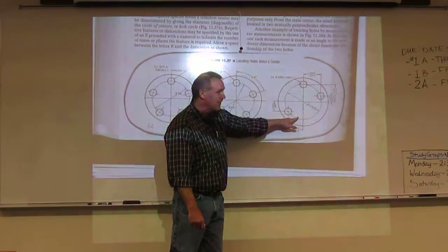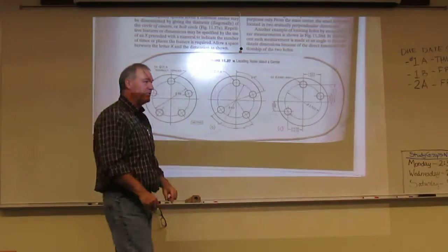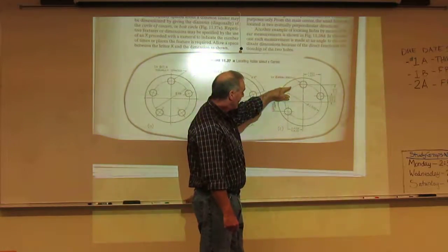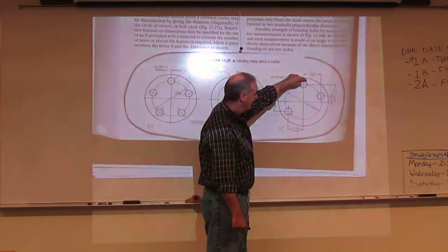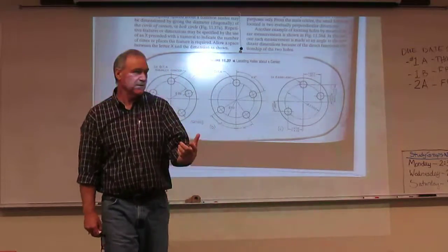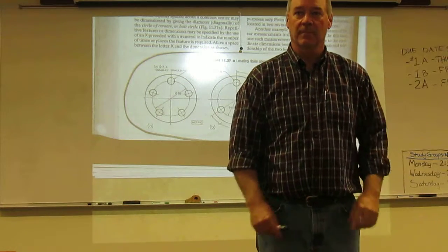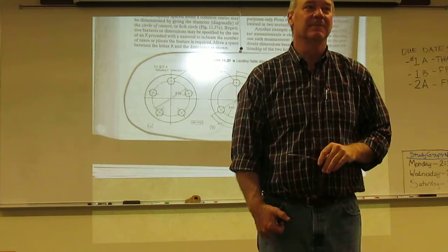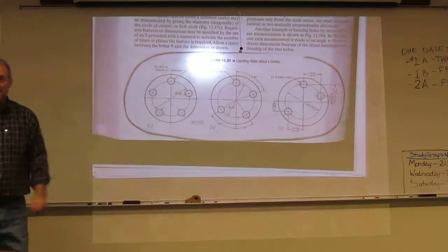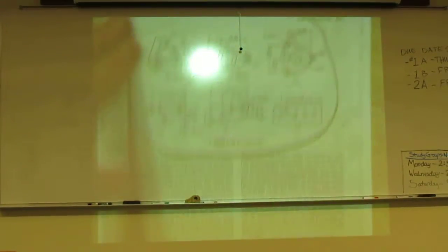The exact same thing's going on here, but here they are using X and Y from a quadrant location. So again, we've got this same circle that's showing the location from center out. This guy's self-locating. These 2, this one and this one, need to be located from quadrants. Whether you go linear or whether you go angle depends on how the part is going to be built. Remember, we always prefer linear versus angle. So a couple good examples on locating. Let's turn the page. There's 4 or 5 of these. We're not going to go over all of them, but